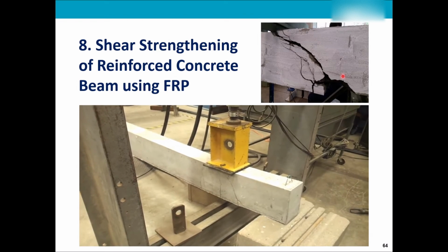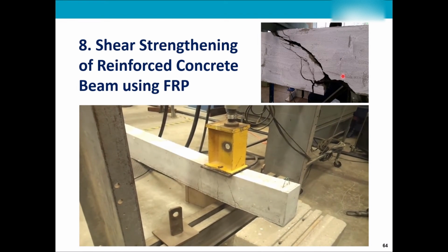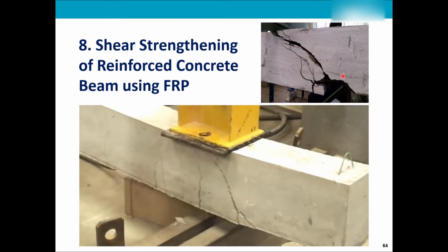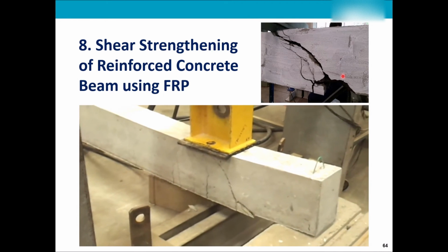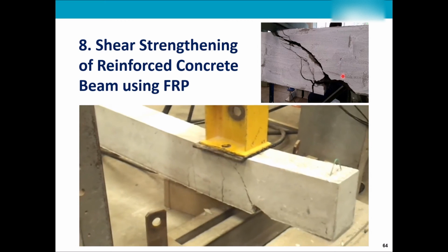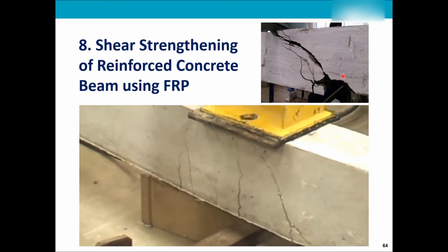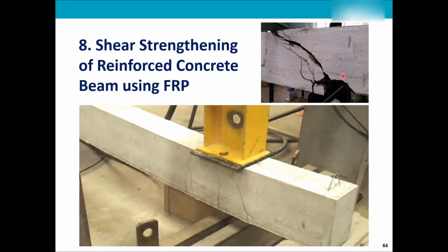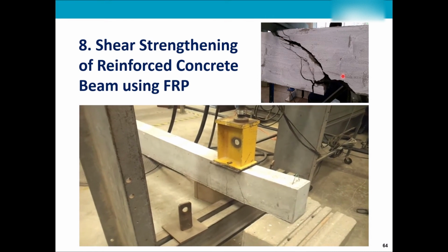So for the flexural, I got the MRD of my section and I compared it to MED. For the shear, I do the same thing as well. I have the VED from my analysis, from ETABS, SAP 2000, Oasis GSA, Seismostruct, any software that you use. I just have to figure out what is the resistance in terms of shear.